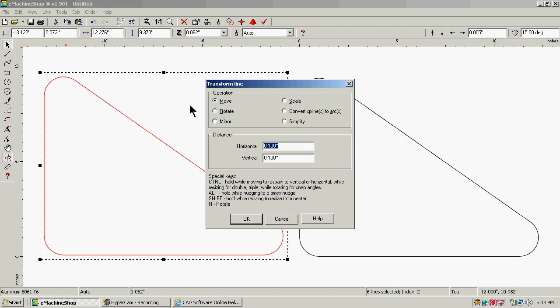When you simplify something, the software will automatically hook all those lines together so that it's one machining operation. I did an engraving for a shell that I showed in an earlier one, and if I wouldn't have simplified that, it had over 5,000 segments per inch, because the drawing really was made up of tiny little lines. So that's what simplify does.